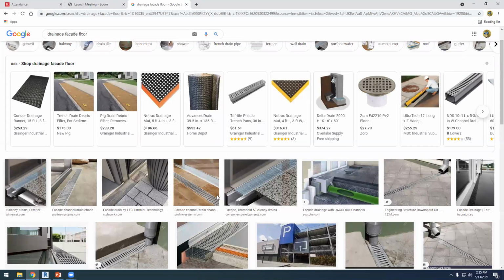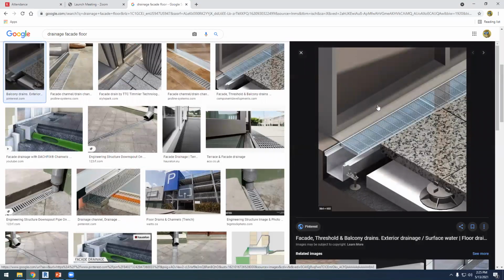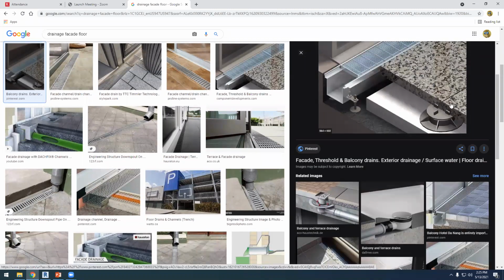So this is the kind of thing that we're going to do. Okay, so this is a wall. In this case, it's a curtain wall, but it can be made of wood or whatever. This is the floor. And we have this element, we have this drainage, and this grill. So if there's some water here, it goes through the grill, and we collect the water here, and then we get rid of it. Okay. We can do this. We have here tiles with these elements to make these tiles horizontal. And this is the waterproofing. This black stuff is always a waterproofing element.